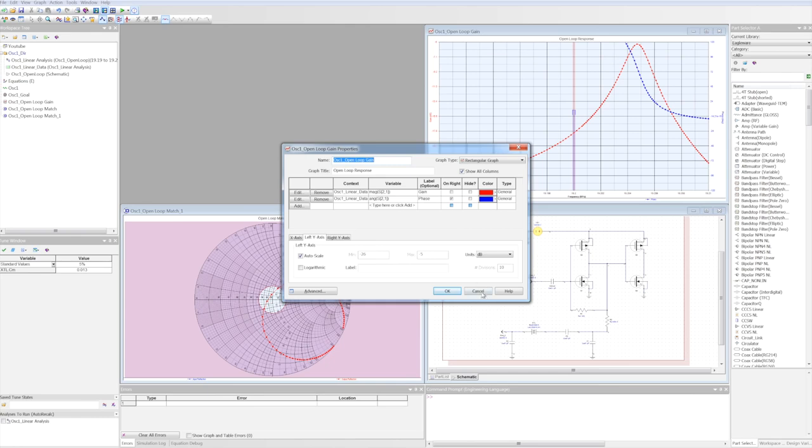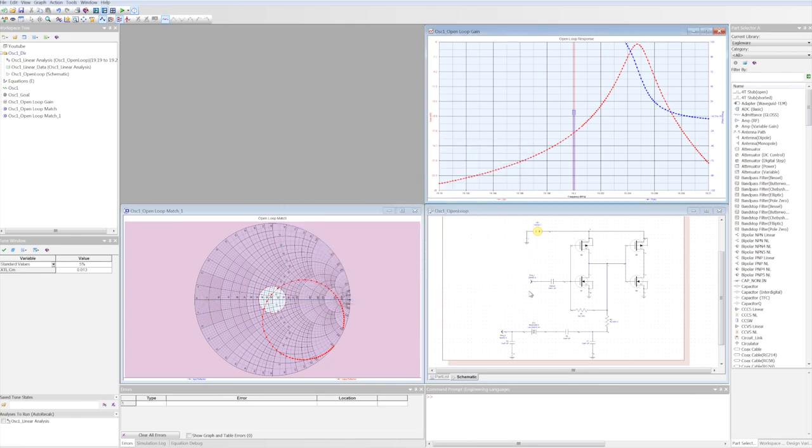The problem with that is, when we actually build this oscillator on the bench, we don't have it open loop, we have it closed loop system. And so we have to close this loop in order for the system to oscillate. And so if we don't have our port 1 and port 2 here well matched to the rest of the circuit, then it's not going to accurately represent the impedance that's going to be seen by the circuit when it's actually closed.